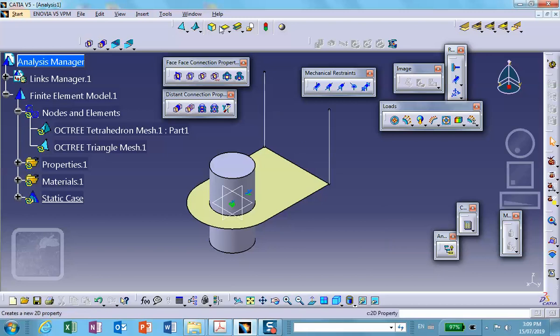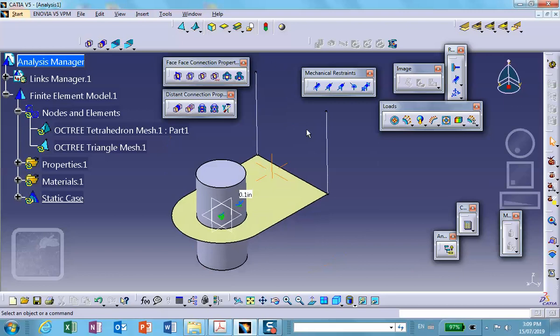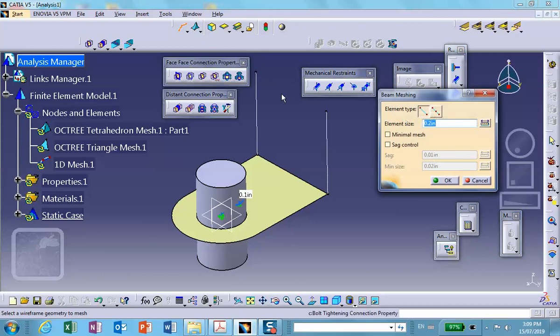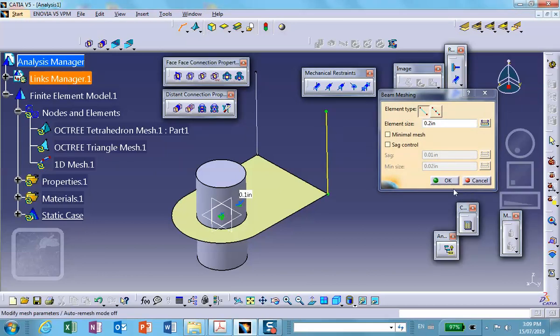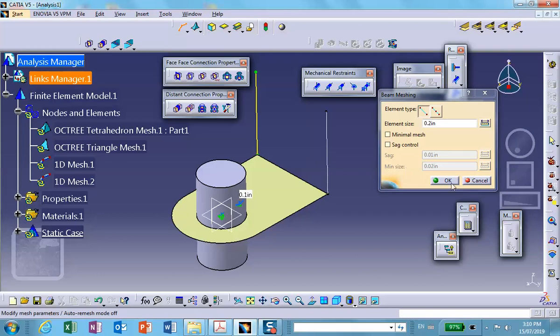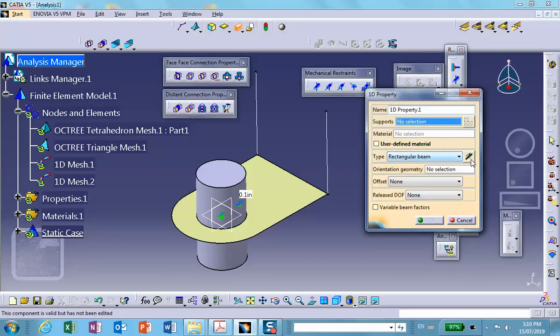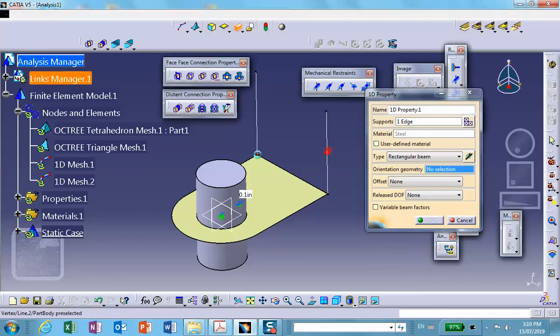All right. Now we're going to do the beam mesh for these. The beam mesher is right there. So we select this. Okay. And then we do it for that one. And then we define the cross section. This was already rectangular, the correct size. So let me apply it to this. The size is correct. For the orientation point, I select this other point. Notice that it turns it around and puts it in the proper orientation.